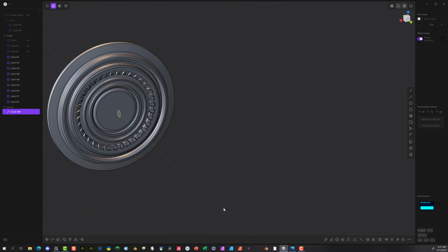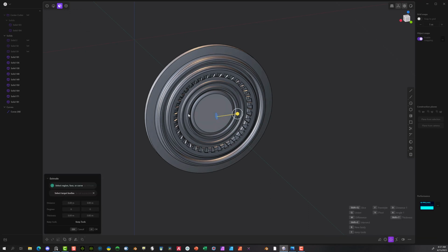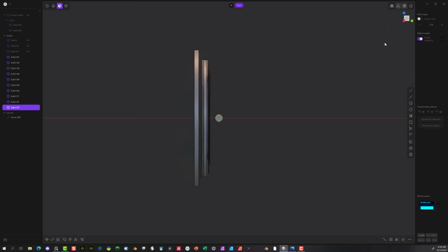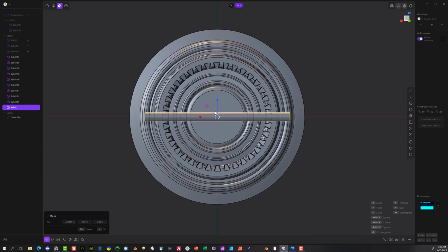So on this one, I'm going to actually create these little rounded things on the top of this button. So I'm going to extrude this. So make sure you're on the face tool, select it, hit the E key, make sure it's on extrude. There we go. That's good. Say okay. Let's go back to the Y, and we're going to go ahead and hit G key. We're going to move this more into the center. Doesn't have to be exact, but that's fine.